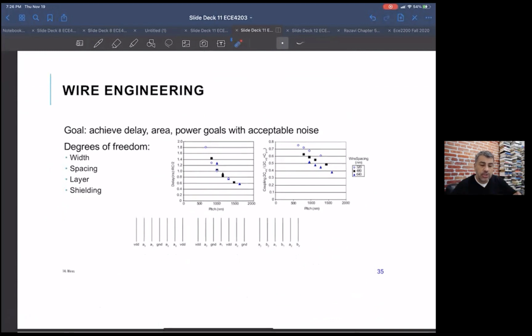When you're figuring out where your different circuits are, say circuit 1, circuit 2, you want to control at every level, both at the gate level and the block level, where things are, so your interconnect is as physically small, the lines as physically short as possible. That's job one.